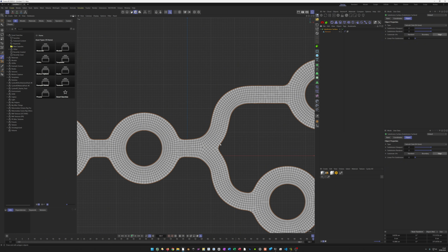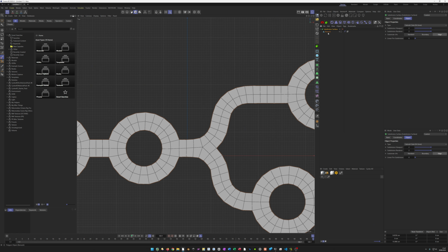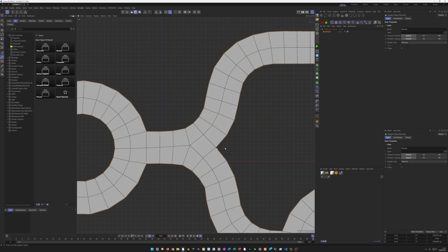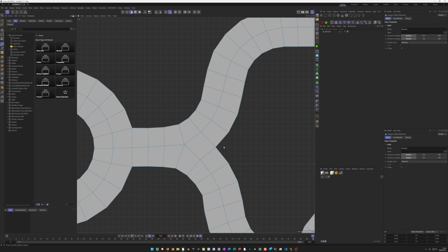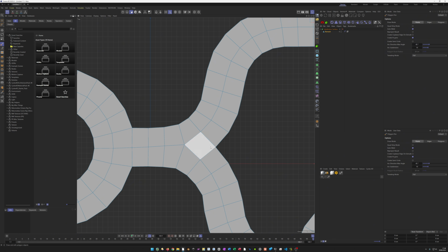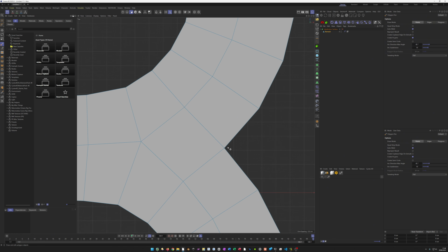You see now it more or less destroys our logo. The logo should have hard, really sharp edges, and not such smooth edges. But if you want everything smooth except this, I'll show you how you can do this. You simply go again to object, polygon mode, M E for the polygon pen, and here we try to make a very